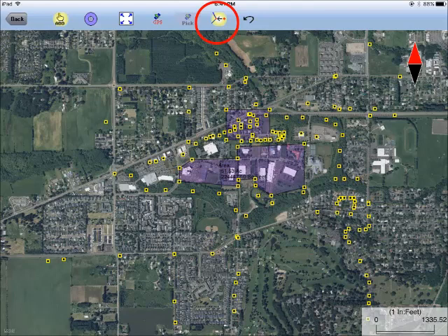If you wish to log one GPS fix to drop a point, then tap on the GPS icon to turn on GPS. And then, tap the Pick GPS icon to record the point. This position will not be accurate unless you are using a high-precision GPS receiver in RTK mode.